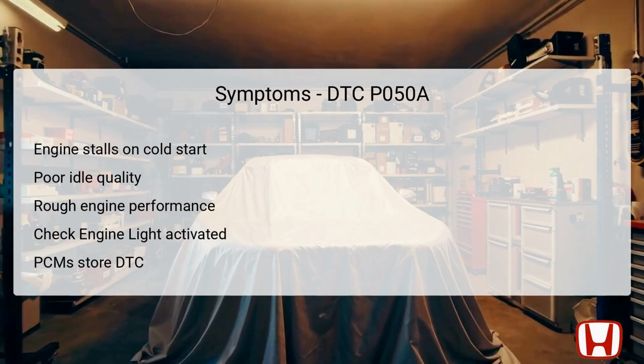When DTC P050A is stored in the system, several symptoms may become evident. One of the most alarming issues is that the engine may stall during a cold start, which can be frustrating for drivers in cold weather conditions. Another common symptom is poor idle quality, where the engine may rev erratically despite the accelerator being untouched. Drivers may also notice rough engine performance, particularly when accelerating or during low-speed maneuvers, which can be disconcerting.